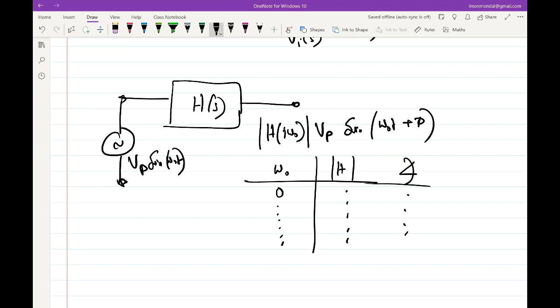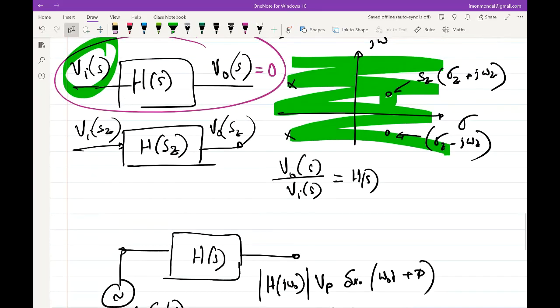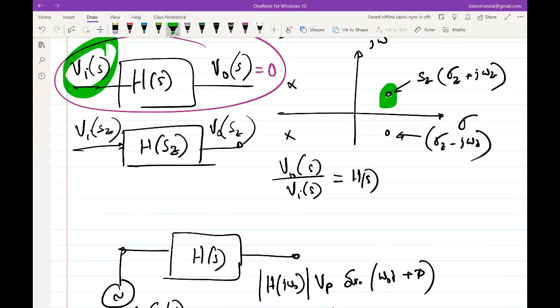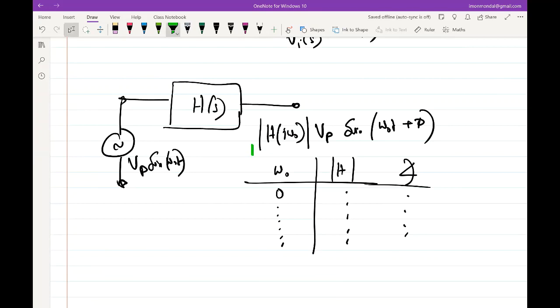What I'm trying to get at here is that when we are trying to find out the frequency of a 0, we are essentially in search of a value of s for which this goes to 0. Correct? However, you should note that S is sigma plus j omega. Correct? S is not only j omega, but omega is the frequency that you are varying.